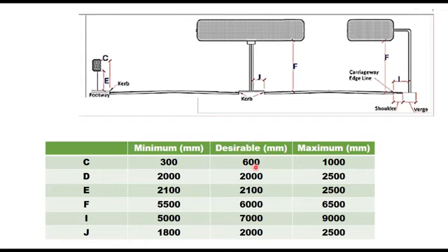On multi-lane roads, the sign may have to be mounted overhead for better visibility, and these overhead signs are considered when traffic volume is high, or when there are 3 or more lanes in each direction, or in case of complex design of interchange, or when there is limited space for ground mounted signs. These signs must provide vertical clearance shown as F here, and this is 5.5 meter to 6.5 meter over the entire width of the carriageway, including the shoulders.